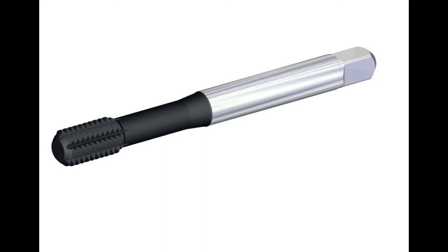In harder materials, you can't use roll taps. What's important to really understand, though, is that the tap drill size is different for the two different systems. Now, taps come with different end geometries. Some of them are called bottoming taps, so they only have one lead-in cutting thread, and the standard ones have about 3 or 4. So the different style taps are customized.